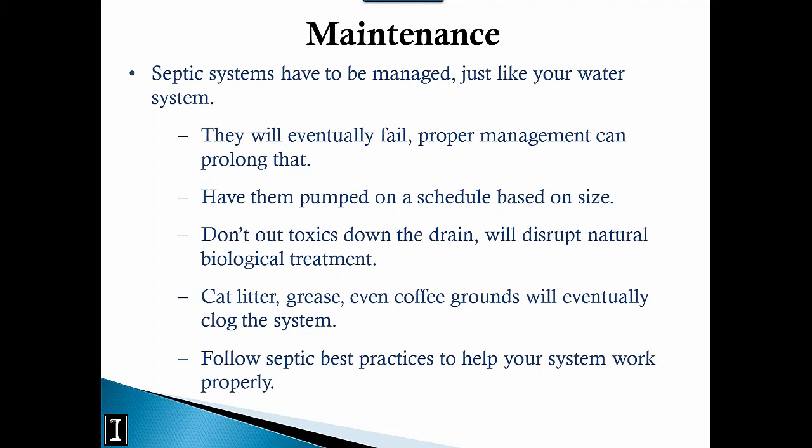You need to have them pumped on a schedule based on the size and the number of people using that system, and not only that, but also your use. So depending if you're using it in a normal fashion, you can really cause problems. As I said before, a septic system works by having the bacteria in the tank break down all the material that's coming in. So, you don't put toxics down your drain.